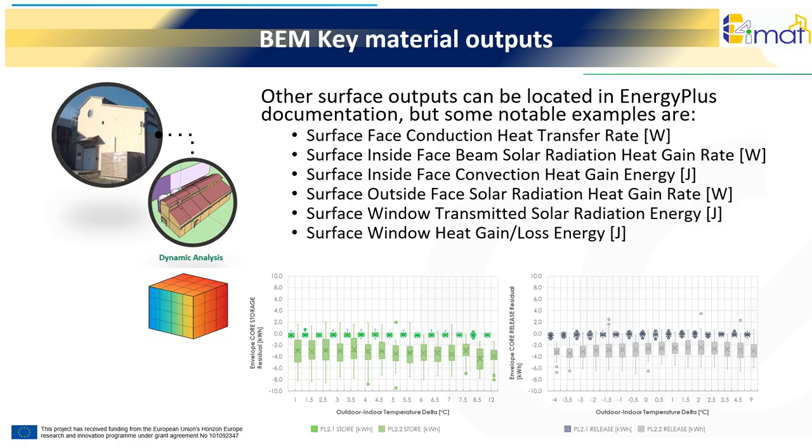On the other hand, the difference between these outside and inside face outputs can display the surface heat storage rate. This output describes the thermal storage situation of the construction, using a sign convention that is positive whenever heat flows into the construction's core. Other surface outputs are located in EnergyPlus documentation, but some notable examples are